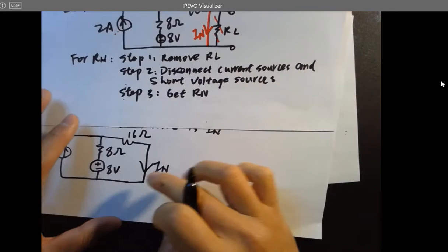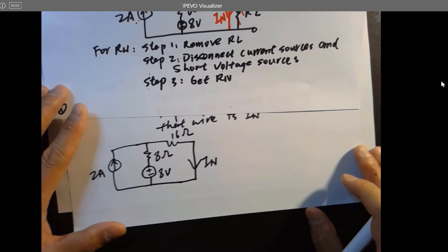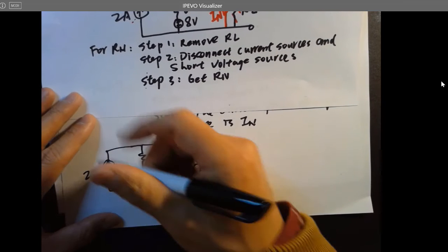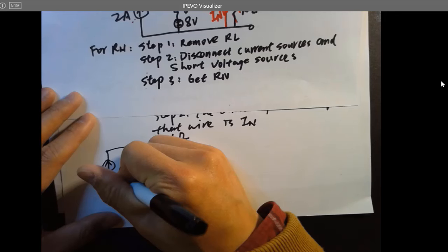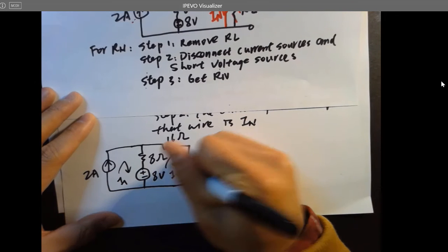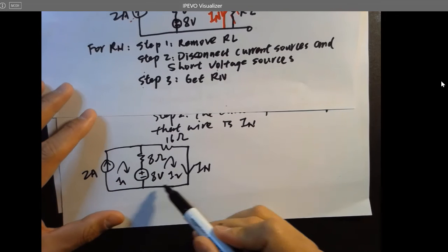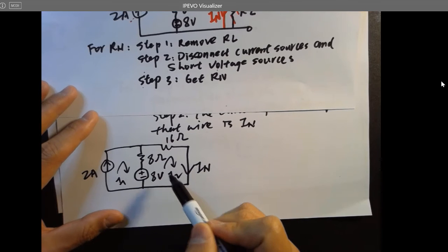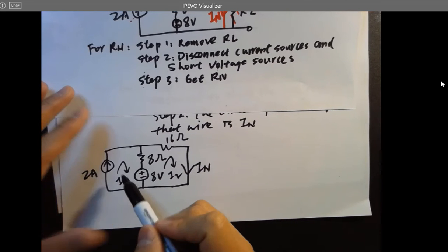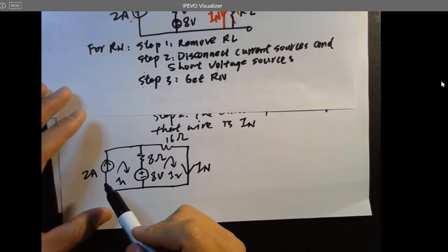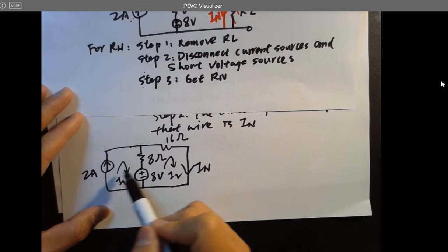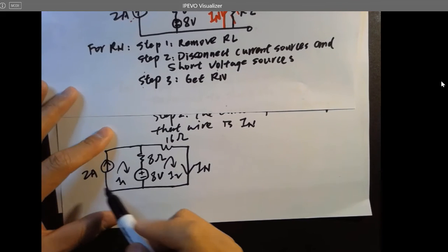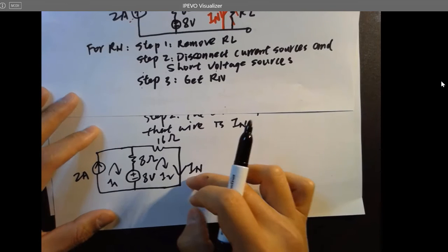You just need to find the current in this wire, and that will be In. How do we find the current here? Of course, you can use the mesh current method. Let's do it. I2 is a mesh current in this mesh, and it's exactly In. I1 is given: it's 2 amps, because I1 is going up, the same as the current source. You just need to calculate I2, which is In.